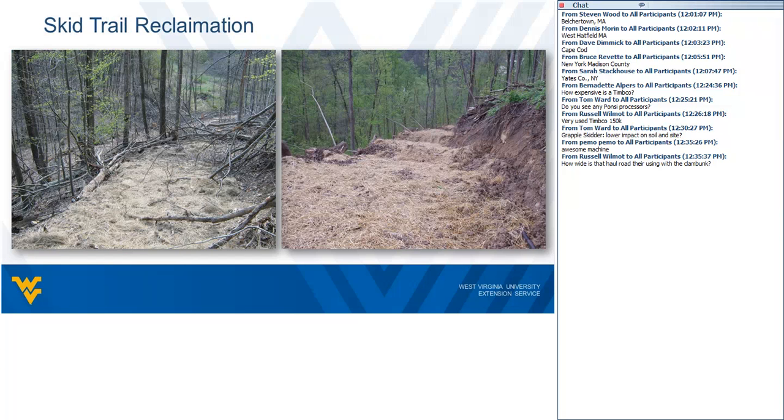Of course, at the end of operations, we'll need to come in and do some reclamation. Reclamation is basically trying to get that skid road to not be a liability into the future. So what we try to do is stabilize it as much as possible and deal with any water that might be rolling down that particular skid road. The steeper the skid road is, the more attention that is required. Very flat skid roads also need attention, but typically over about 10%, you want to spend a lot more attention on it, and things that are exactly flat, you might want to spend attention on those.